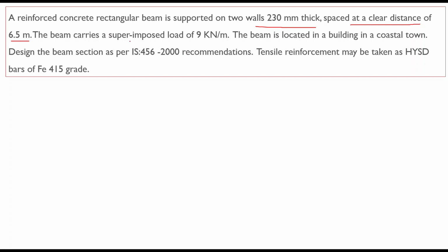The beam carries a superimposed load of 9 kilonewton per meter. So the live load is given, that means a superimposed load of 9 kilonewton per meter. The beam is located in a coastal town. So the location of the building is mentioned in the design statement.